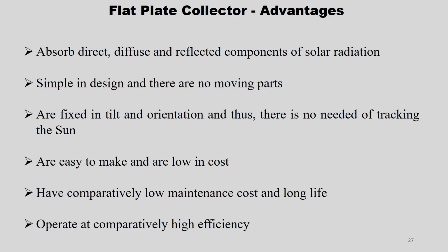Then next, what are all the advantages of the flat plate collector. It absorbs direct, diffuse and reflected components of radiation, it is simple in design, there are no moving parts, and the tilt and orientation are fixed, so no need for tracking the sun. It is easy to make and low in cost, has comparatively low maintenance cost and long life, and operates at comparatively high efficiency with less labor and complexity. So, that is where the advantage of getting comparatively high efficiency for less investment lies.